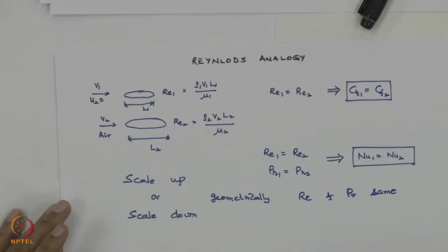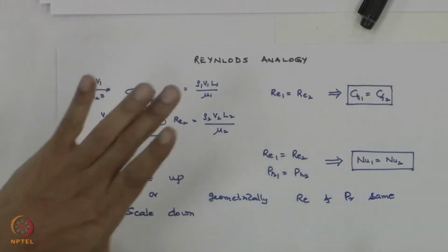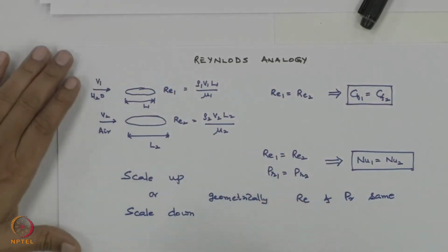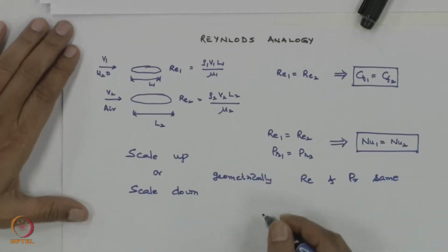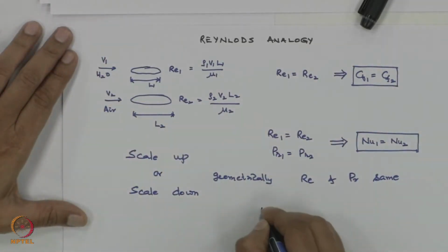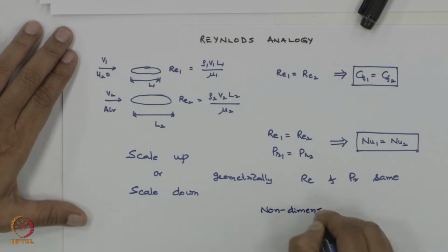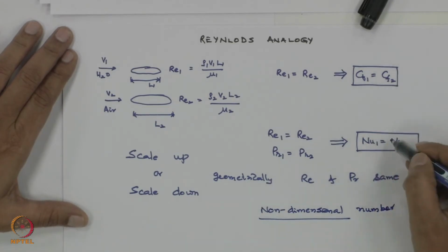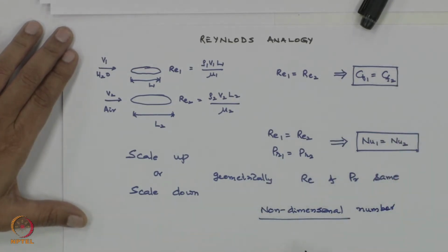Okay, so this is the understanding of non-dimensional numbers. Whenever we do an experiment, we would like to come up with non-dimensional numbers. Why? Because I can generalize all my results and put them in terms of my Cf or Nusselt number, in terms of non-dimensional numbers. We don't keep dimensional numbers.